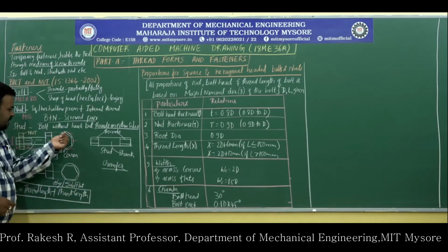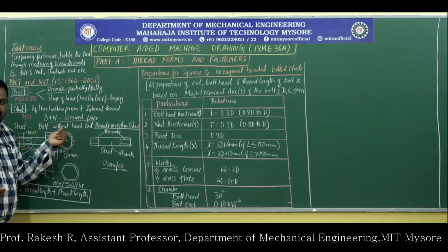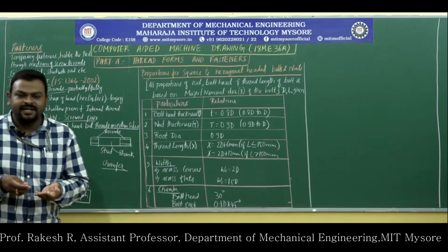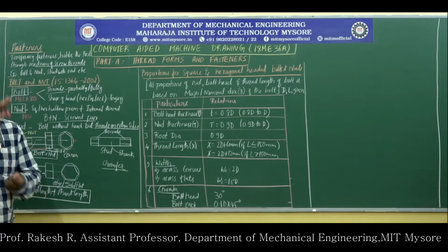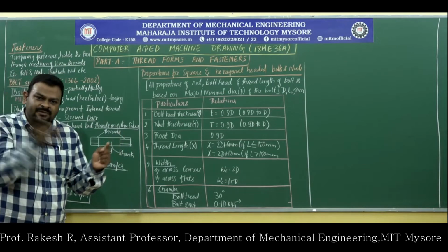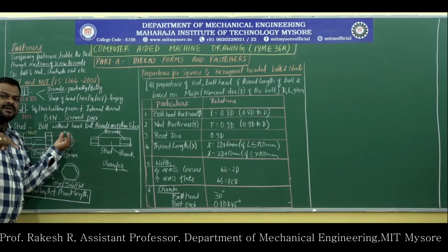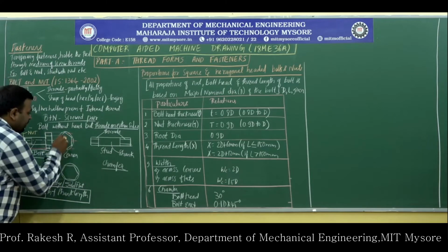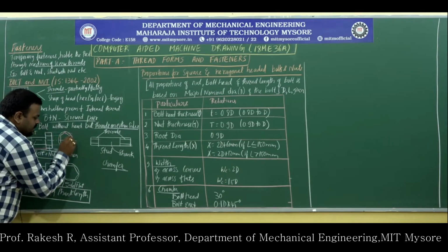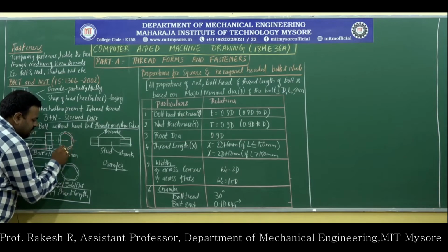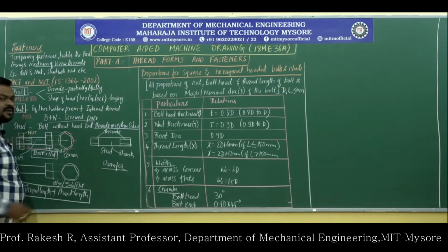So say for example, here there is a sharp surface. I need to avoid that. How to avoid it? Yes, I need to give either some radius or some angle. I need to make a sharp edge into a smooth edge. So I will be smoothing this, I will be smoothing this like this, I will be smoothing all of these.